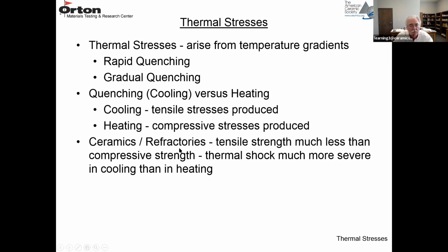So ceramics, refractories, whatever way you look at them, the tensile strength is always much lower than the compressive strength. So thermal shock is always much more severe in cooling than heating. So the cooling cycles are what really does the damage to a refractory.